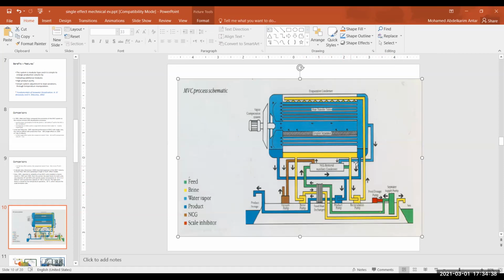Actually, in this specific layout, it is mixed with the brine, and after that, the whole mixture is taken to be sprayed at the top. We have a brine recirculation this way, and we reduce the amount of additives that should be given to the seawater. The third kind of flow here is for the desalinated water, or the product water.